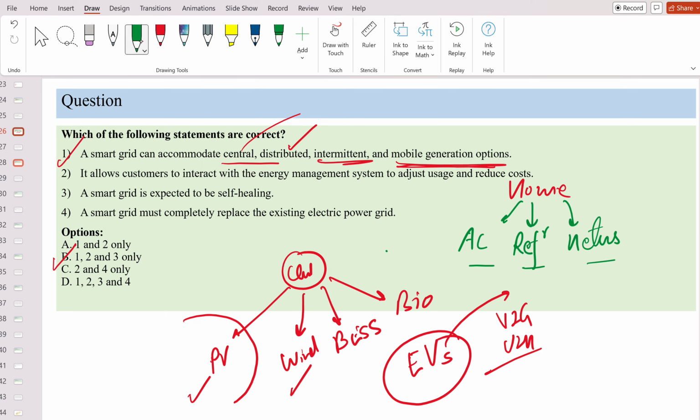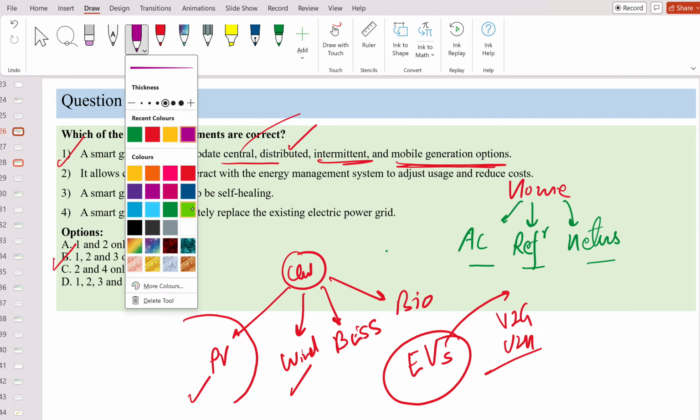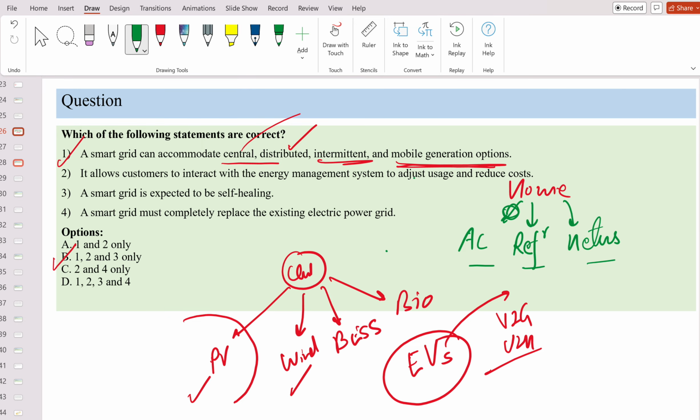You just put a smart device in between, which monitors and gives commands to the EMS, the energy management system. Suppose it is peak load time: you curtail the AC or refrigerator to reduce power, so that energy consumption is not high in the time frame where the tariff rates are higher.